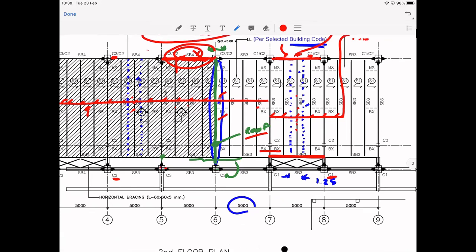And you see, there's one in between the 2 different live load zones. So for this one, you use the same size as the ones in the heavier live load zone, okay? So it should be that simple.